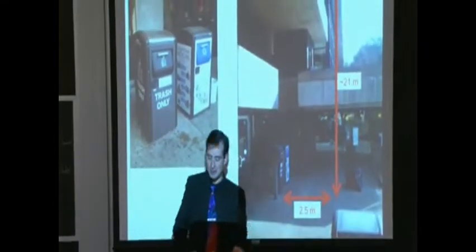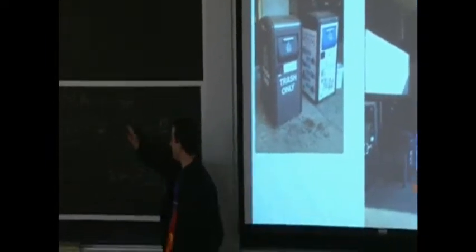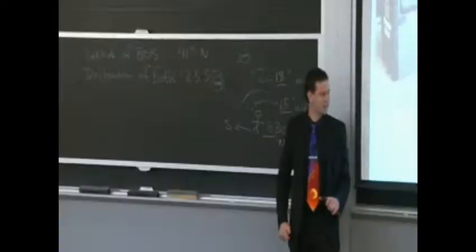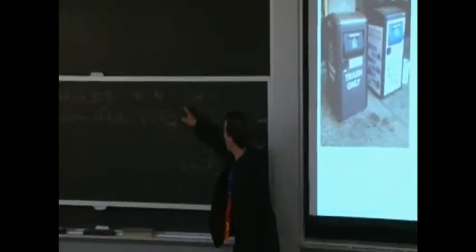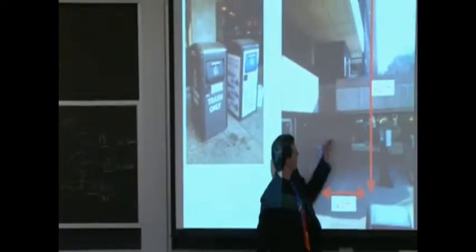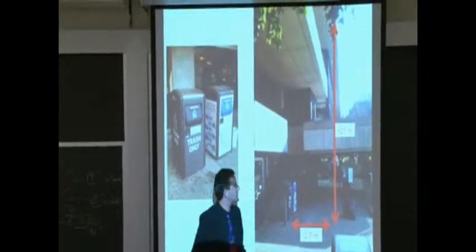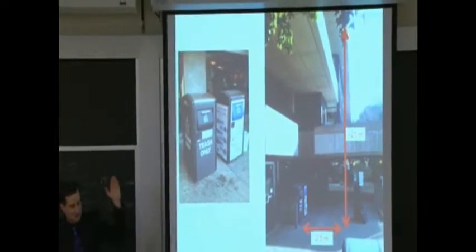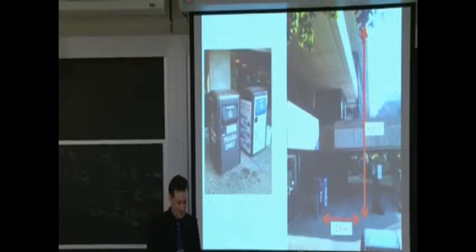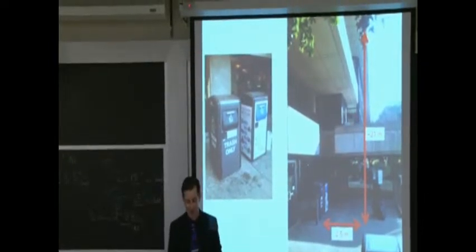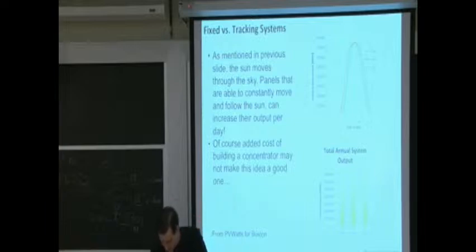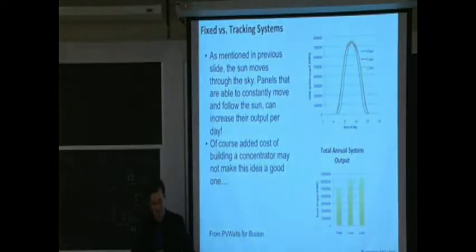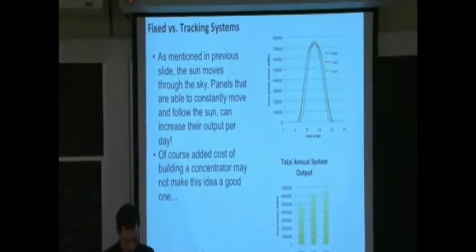But it was an example of somebody not really thinking much about the direction or the angle of the sun in the sky. They probably installed it sometime around March, right when the snow started to melt, and the sun was right around here, right? And so the angle was around there, and it made it into the trash collectors. But as the summer came along, it got shaded. So it's something to keep in mind when doing a solar installation. It is important to calculate these things, and I just pick out one small example. I'd encourage you to walk through. I was going to have that be a small little in-class example, but since we're running short on time, I'll just give it to you like that.